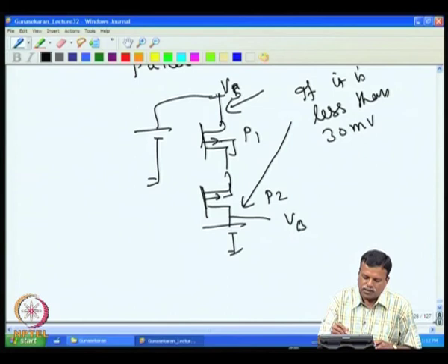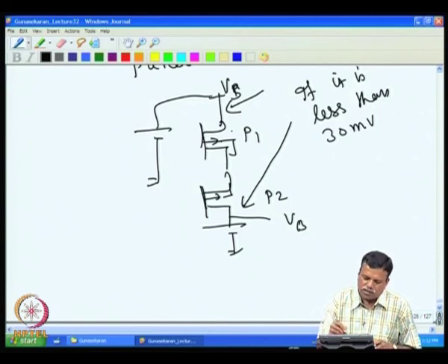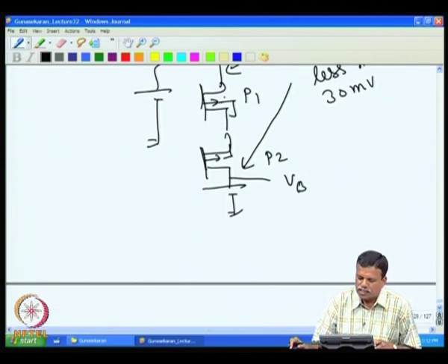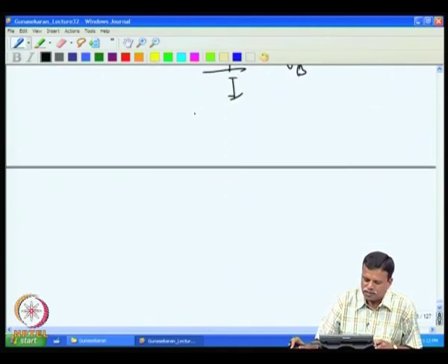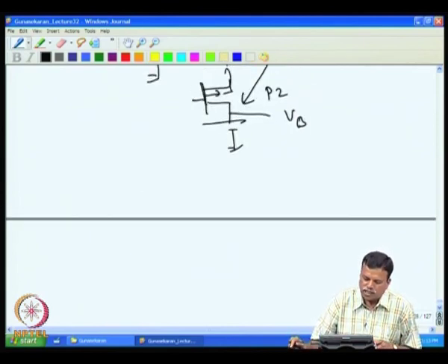Only if the solar cell voltage is more than the battery voltage, you will switch on. So, to detect accurately, P1 and P2 are switched off, then solar voltage and the battery voltage are measured, and then the decision is made to switch on the battery.